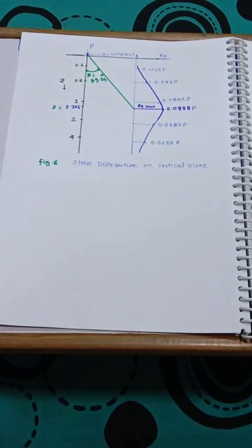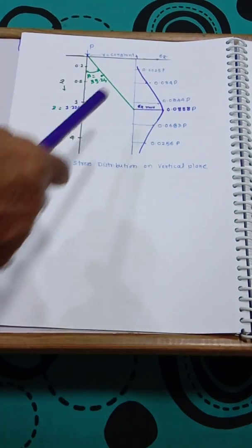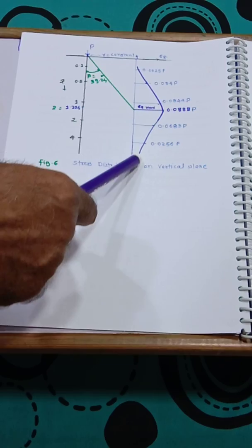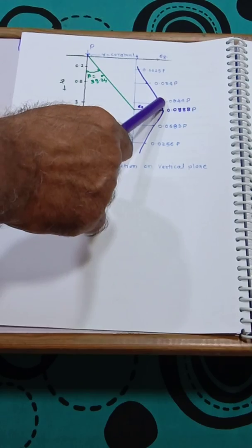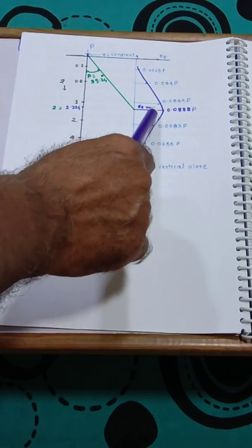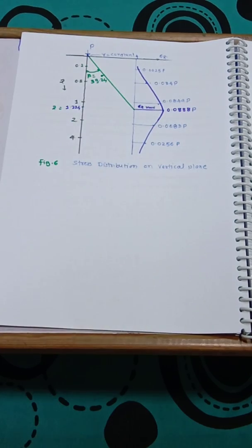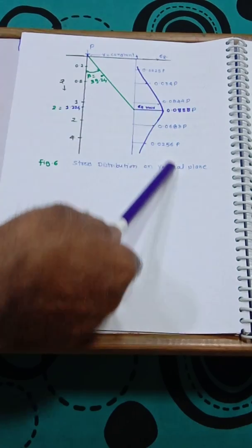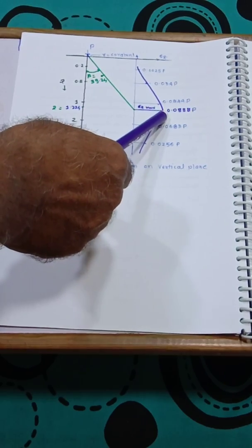So we got this stress distribution. You can see R is constant at a depth. This is the constant plane and Z is a variable. So you can see how the stresses vary. First the stress is very small, then it increases, then again increases. Between 1 and 2 it was maximum at 1.224, which was the highest, 0.088P, then it decreases. So this shows that the stress does not simply increase or decrease linearly. It has a trend: first it increases and then decreases.